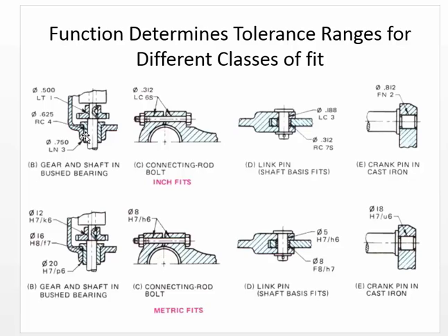And then we have the bushing itself, which is press fitted into some kind of device. And that press fit is known as an interference fit. And the interference fit in this case is so that the bushing won't turn and the bushing won't come out readily. You have to press it in and press it out.